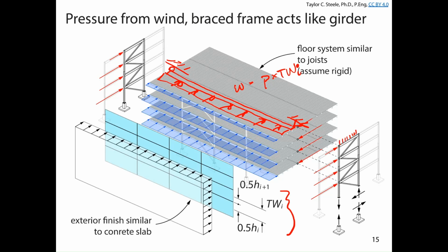But we're going to connect the floor system so that when there's a horizontal force on that floor, the horizontal force gets transferred into the beam of the braced frame, and the reaction provided by that braced frame to keep the floor in place is going to be the action of the floor pushing on the braced frame. Okay, so basically what we have here is reaction of the floor system, and those reactions are going to be the point loads acting, and we're going to assume more or less at the joints or at the elevations of the floors acting on the braced frames.